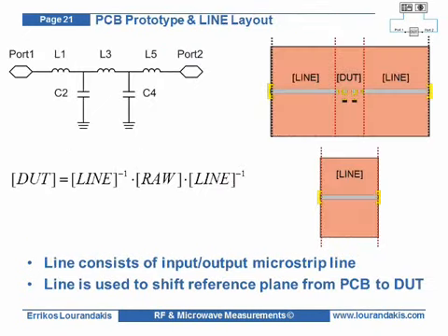The de-embedding can be performed directly by the VNA or by post-processing of the measured raw S parameters. All we need for the de-embedding are the S parameters of the microstrip line used at the input and output terminals of the PCB. The S parameters of the line can be obtained either by measuring a new PCB which consists only of the microstrip line itself, or by performing an electromagnetic simulation of the line structure.